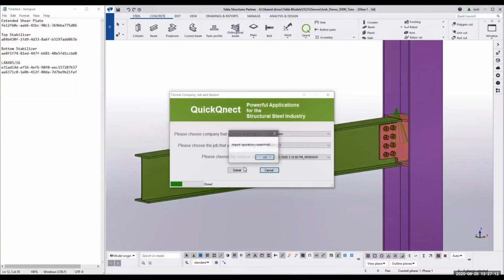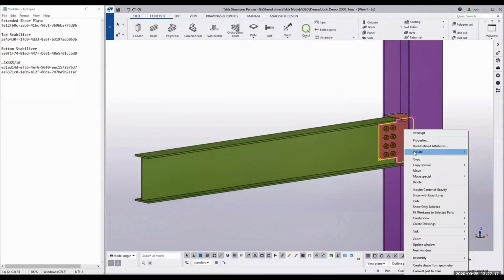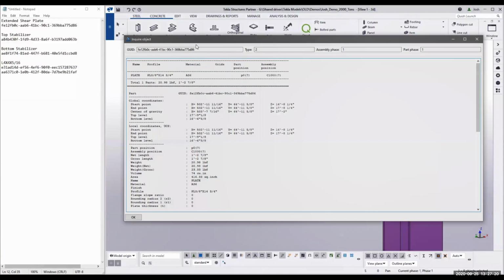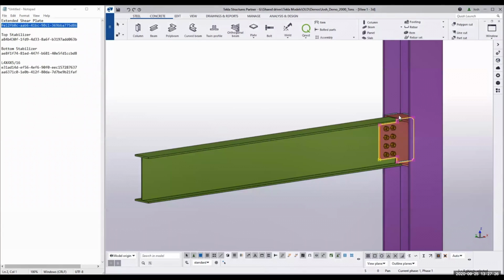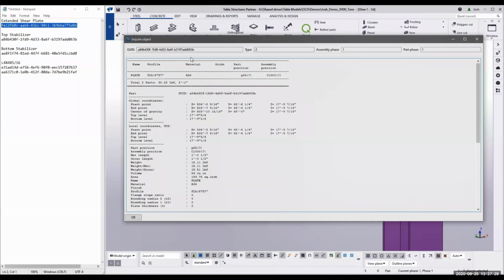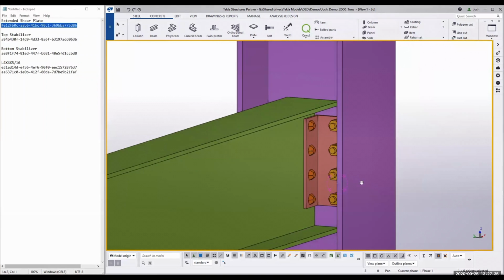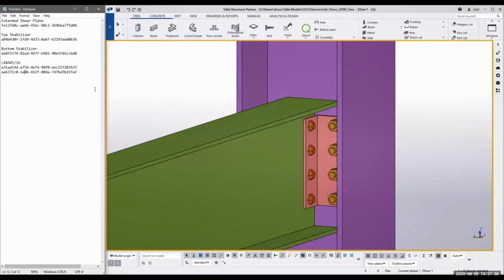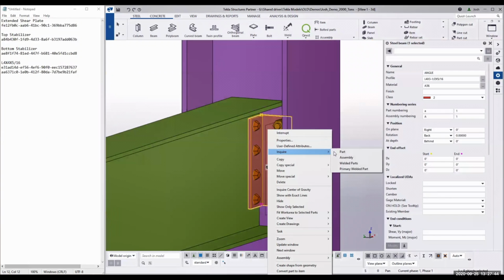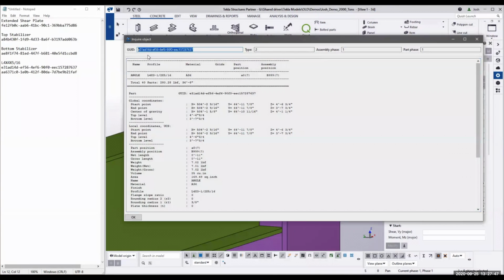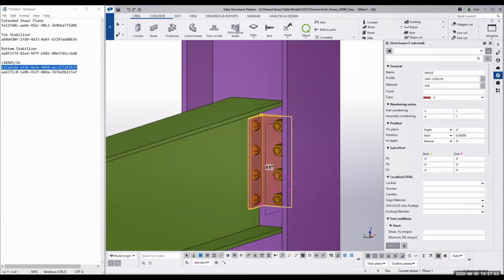So the beauty of this is we did get an extra column of bolts, so things did change, but we didn't remove any materials and add new materials. So we still have the same GUID. What we've done is actually just adjusted the materials that are already there. And if the materials didn't adjust at all, they just simply stay. Nothing changes. So 4x4 5/16. Well, now it's 4x3.5 5/16, but it still has the same GUID. Now, the benefit of this is very minimal impact to your shop drawings.